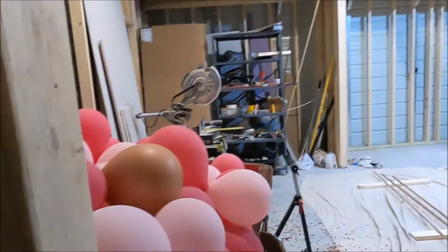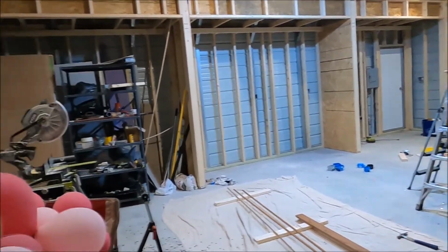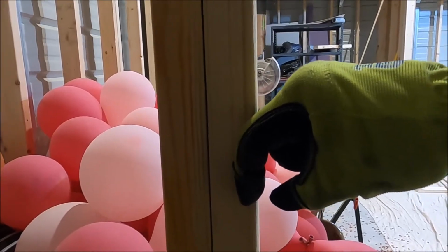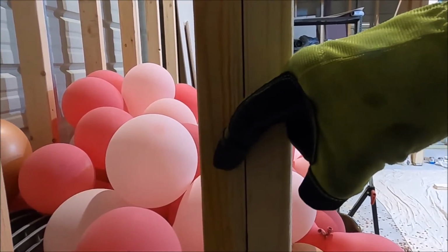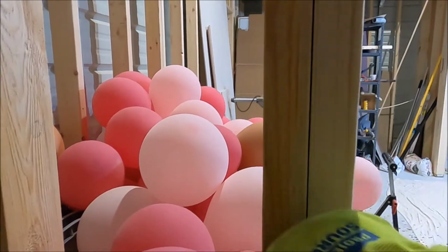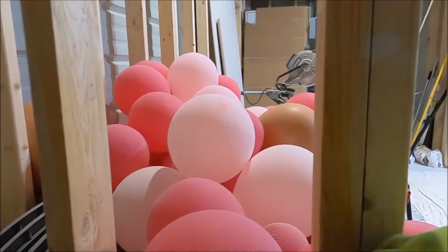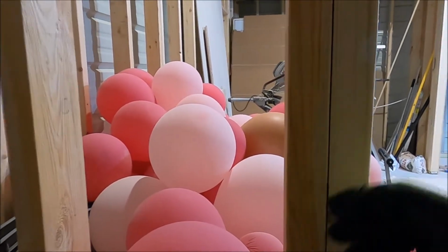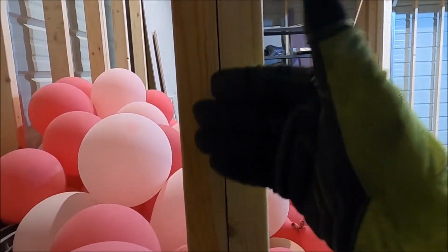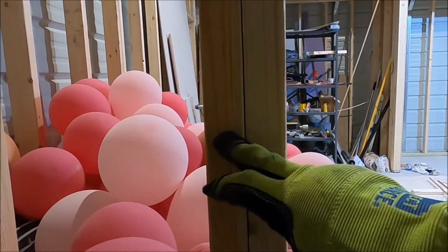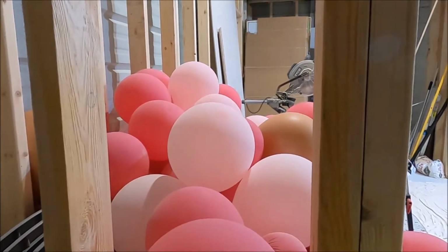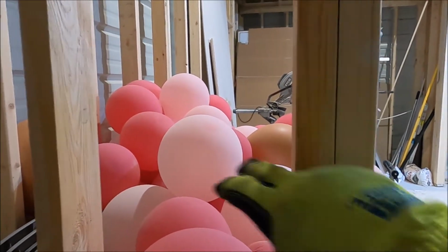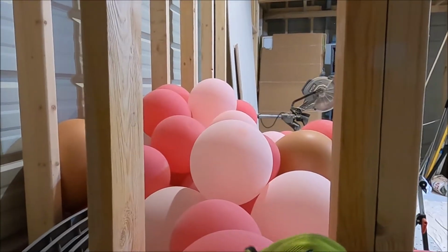The doorway in the office is 2 2x4s thick. So consider what's going to go on here: you're going to have a door that's going to fit inside here. Then you're going to have some trim, and then what happens on this other side? I'd like to put a switch as close as I can to the door, but if I mount it right here, I'm going to be stuck with the door and the door casing and everything. So what I'm going to do is put another 2x4 on here, about a foot long or so it doesn't split out. Just nail it on the inside. That'll give me another 1.5 inches of space.